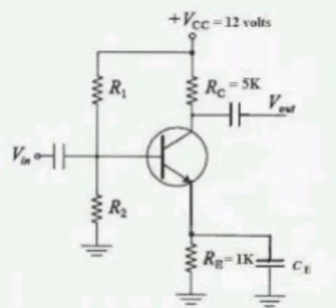Assume an ideal 10-bit ADC with V reference equal to 5 volts is used to sample a 1 volt peak-to-peak sinusoidal signal that has a 2.5 volt offset. What percentage of error can be expected in the peak voltage measurement due to the quantization effect of the ADC?